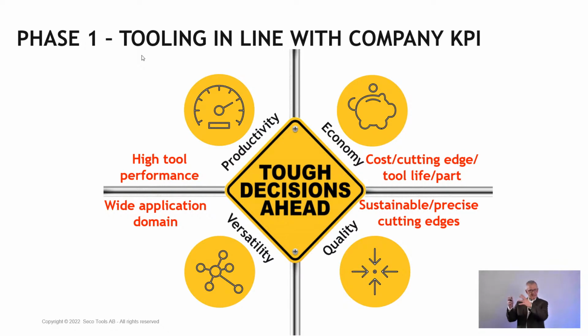And both are best in their domain, and so on and so forth. If, however, your wide application domain view on cutting tools is the priority, because you look for versatility in your production, then perhaps we could ask the question, why not stay with a square shoulder milling cutter? Because with a square shoulder milling cutter, you can do face milling.